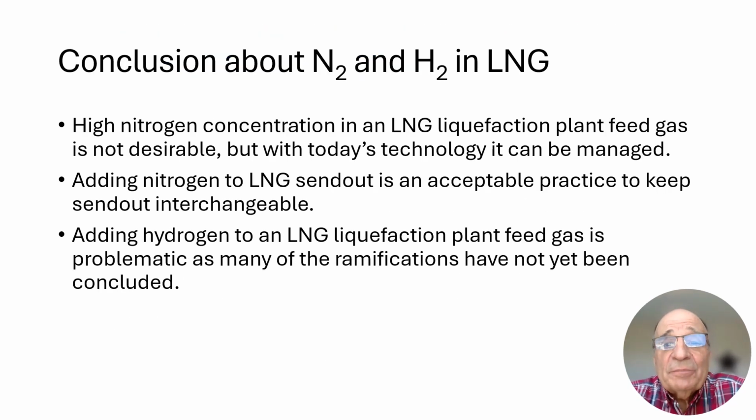Well, our conclusions about nitrogen and hydrogen in LNG are as follows. High nitrogen concentration in an LNG liquefaction feed gas is not desirable, but with today's technology, it can be managed. Adding nitrogen to LNG send-out is acceptable practice to keep send-out interchangeable. Adding hydrogen to an LNG liquefaction feed gas is problematic, as many of the ramifications have not yet been concluded. More research is needed.